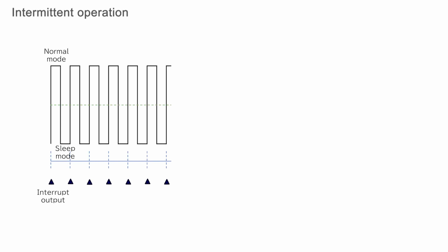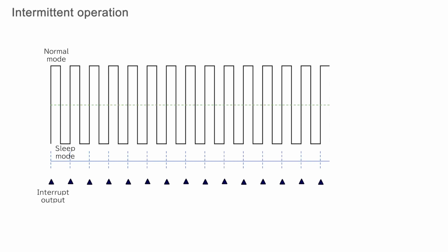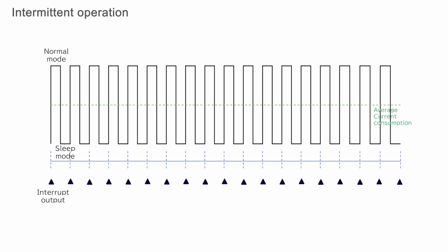The wake-up function of Epson's RTC module can be set to a period of less than a second. For example, if you need it to operate constantly and think that intermittent operation is not possible, but constantly means that operation once per second is sufficient, then this wake-up function may be sufficient. Intermittent operation at short intervals makes it possible to lower the average current consumption of the system.